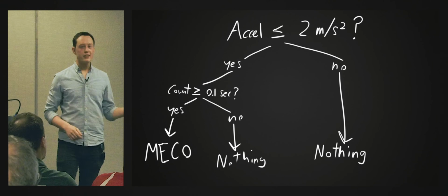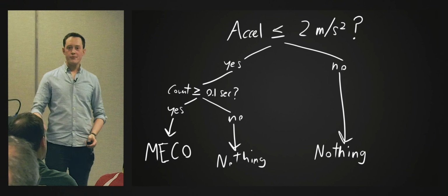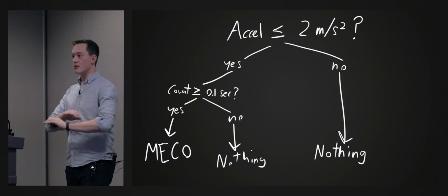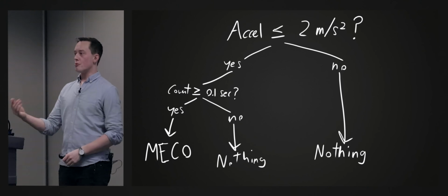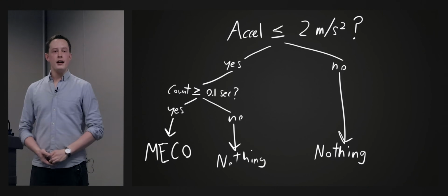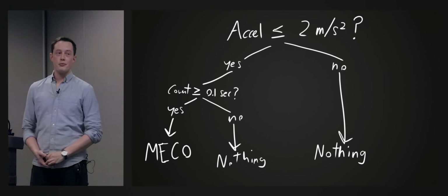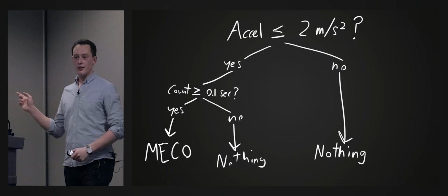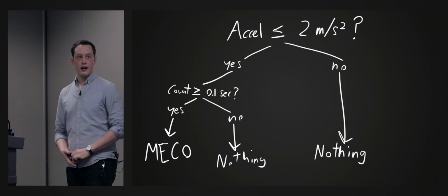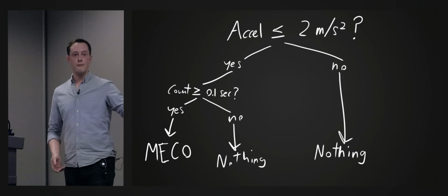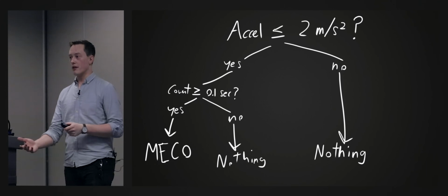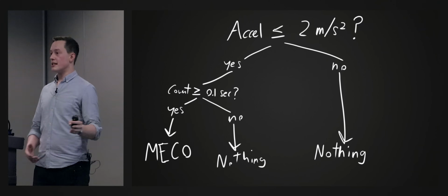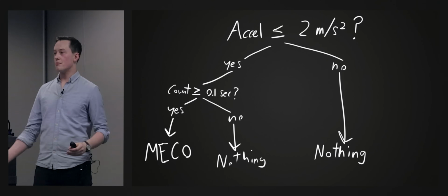So the Rocket Lab Electron uses electric turbopumps, right? And that means, I am pretty sure, don't totally quote me on this, I'm pretty sure they burn their tanks completely to depletion instead of having a low propellant sensor. And when they do that, they don't actually have control over exactly when their vehicle burns out. So on the stream, you will hear them call out burnout detect mode. You'll hear the flight director call that out, and that's when the vehicle is switching into a new state. A lot of launch vehicles do use state machines as well. And so it switches into a new state where it's looking at probably something like this to detect when it has burned out and then start the stage step sequence.